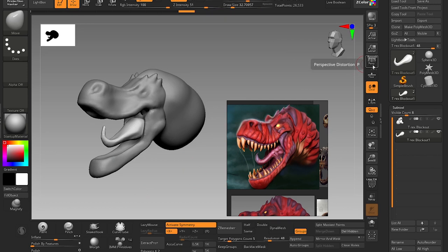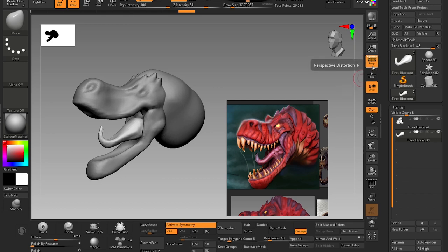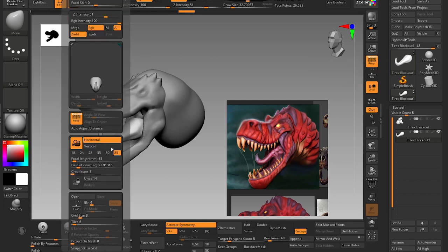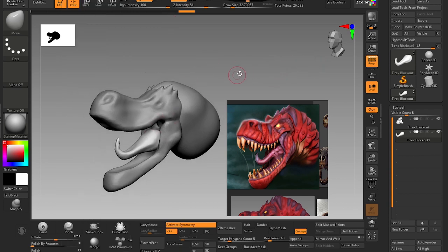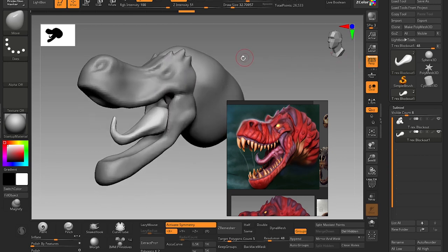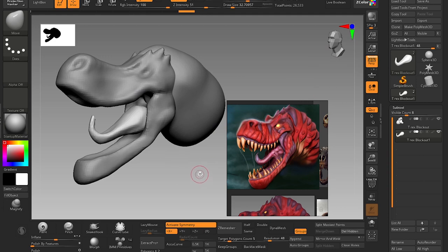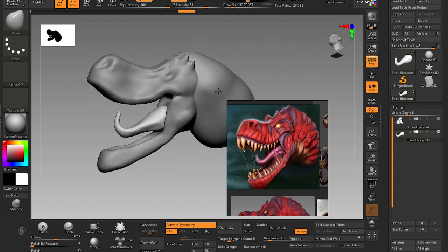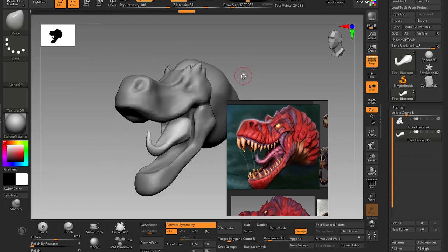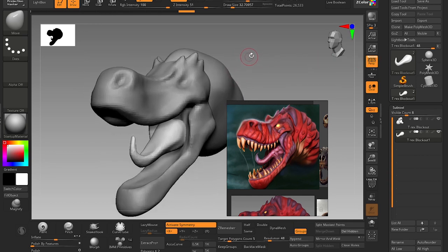And now that perspective is on, dynamic perspective is something you need to switch on most of the time. The default perspective is usually 50. If you go to Draw, you will see this 50 camera focal length; I turn it to 85. 50 is too much focal length for me. It's personal preference, do as you please. I try to switch it on and off, but for now we are at a stage where we need perspective on, because most other 3D software uses perspective. So turning perspective on usually helps a lot.